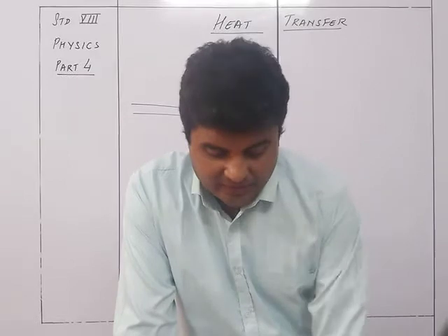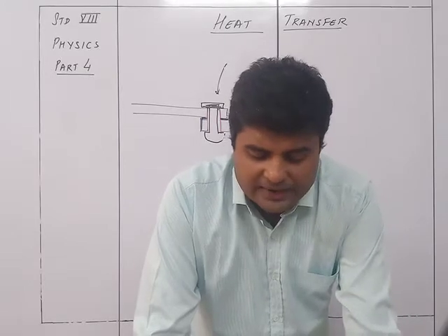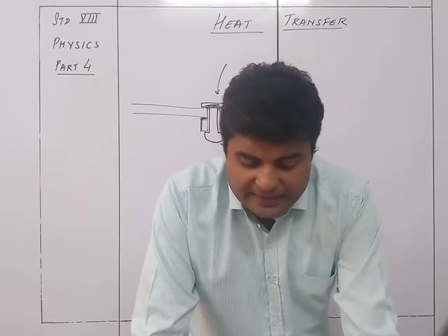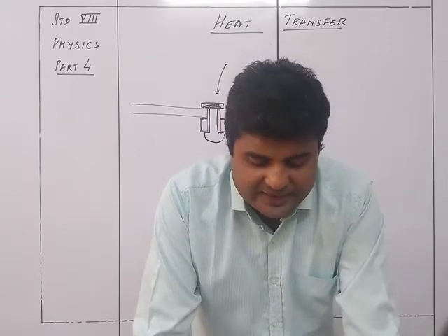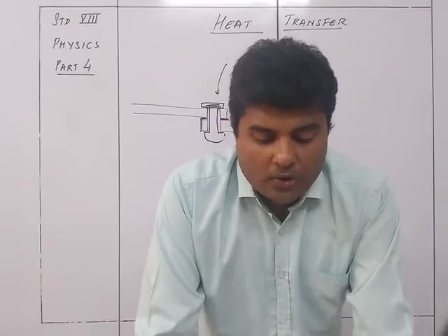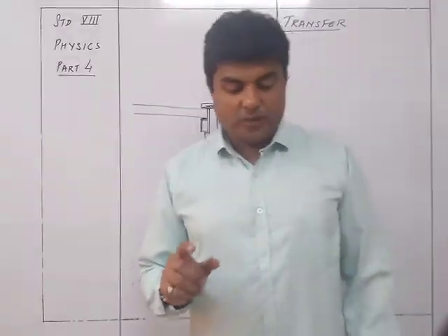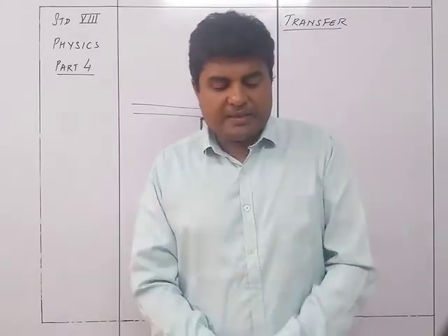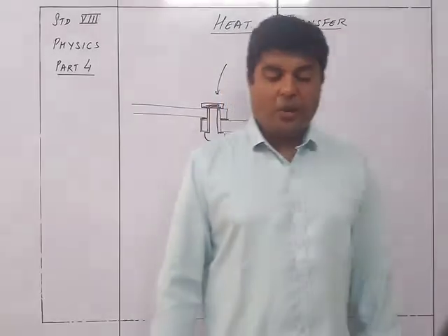So let's see what is given here. Riveting. For joining two steel plates, they are placed one above the other and holes are drilled through them. The rivets, small steel rods, are heated red hot and then inserted in the holes of the plates. On heating, the rivets become soft, so their ends are easily hammered into heads. Now the rivets are allowed to cool. On cooling, they contract, but they cannot regain their original size, as they have been hammered. So they bring the plates closer and firmly grip them together, making the joint waterproof or steam-proof. Such riveting is used in joining steel girders, boiler plates, etc.